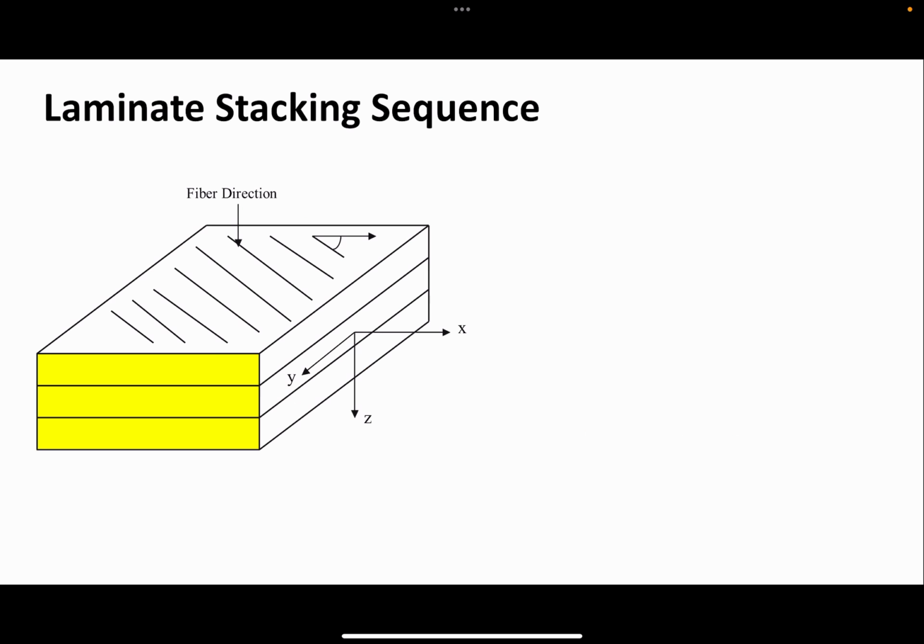And then you have possibilities of laminates where you have different materials even. So in that case, what do you do? For example, here it's 0, 45, minus 45, minus 45, 45, 0. So it is symmetric about this plane. So then you say 0 slash plus minus 45, close, write S for symmetric. So it's 0, plus 45, minus 45, minus 45, plus 45, and then 0 again. If you write minus and plus 45, then the minus layer goes first.